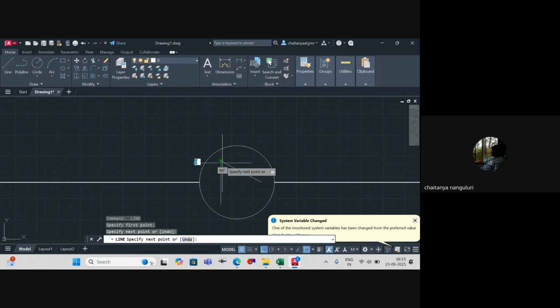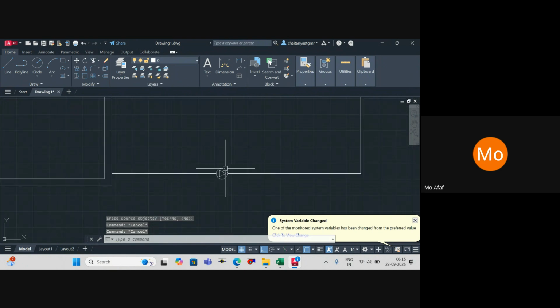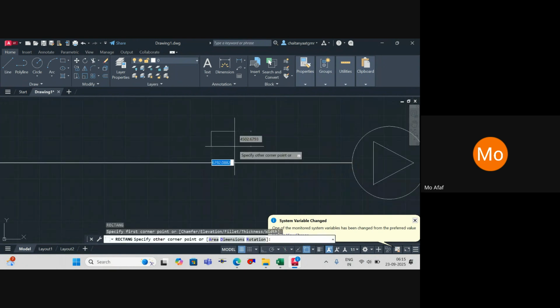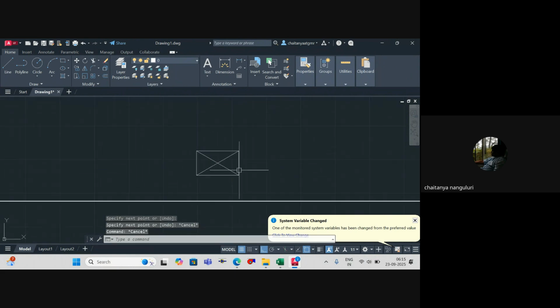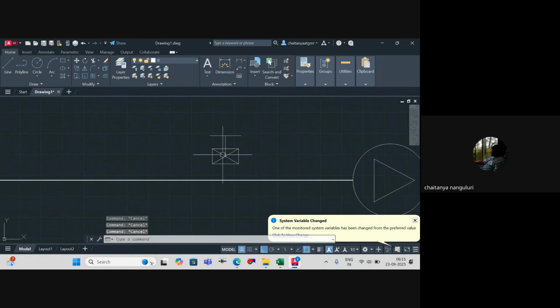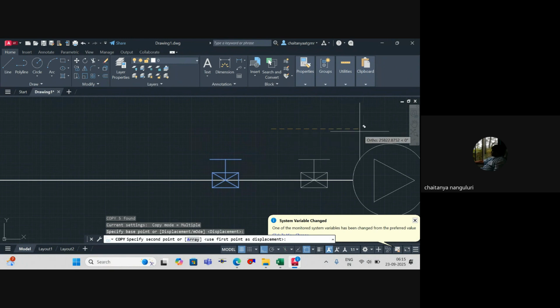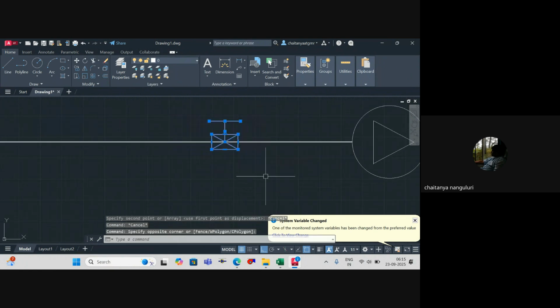You're comfortable with CAD and Excel sheet, right? Instead of using pen and paper, I'm comfortable with this. So at the inlet, I'll definitely have a butterfly valve. Obviously I'll have a butterfly valve at the inlet, and definitely I should have a strainer, because whatever the fluid is, it needs to be cleaned before the impeller, or else the impeller can get hit and lose its head properties.